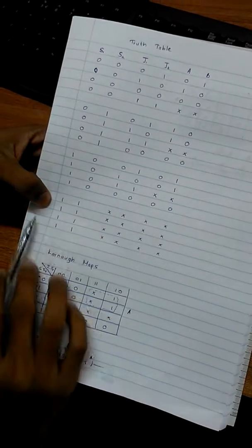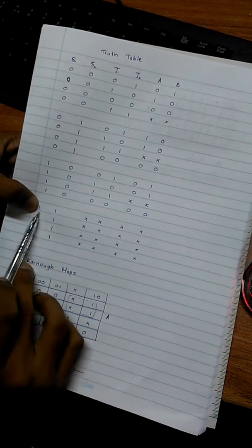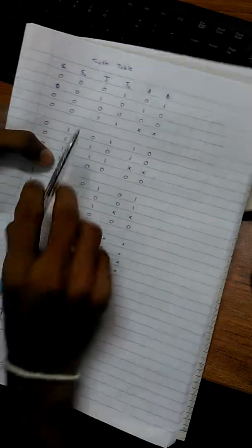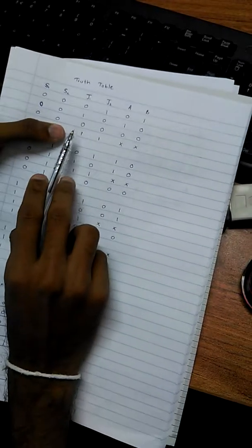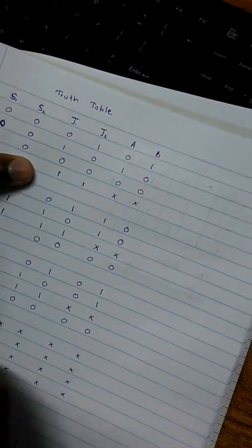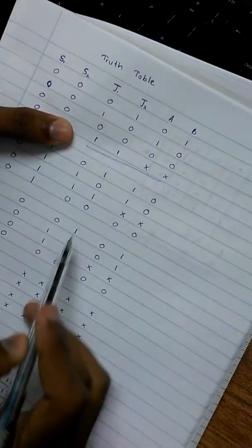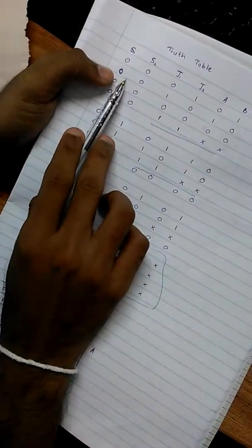First of all, we ignored the terms where both S1 and S2 switches are high because it is impossible in a practical situation. We also ignored the situation where both J1 and J2 are high because it is also impossible, since we cannot switch on the joystick for forward and backward directions at the same time. So here we ignore these terms,